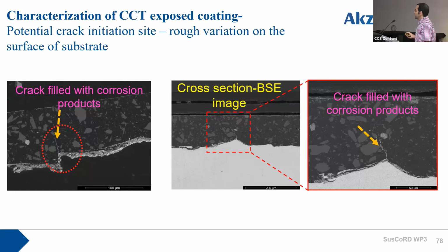One is that this stress concentration point results in the crack formation, and then the crack propagates through the entire coating thickness and allows transport of the environment to this point and results in the corrosion formation, and then corrosion penetrates into the crack.